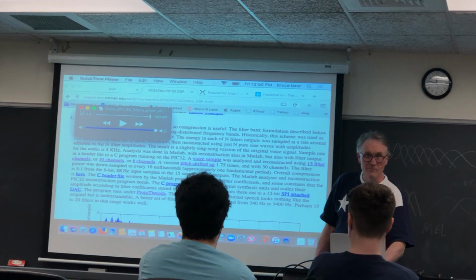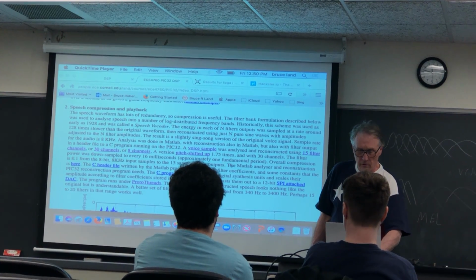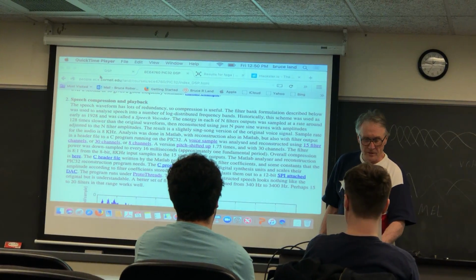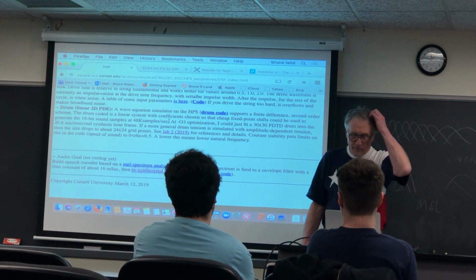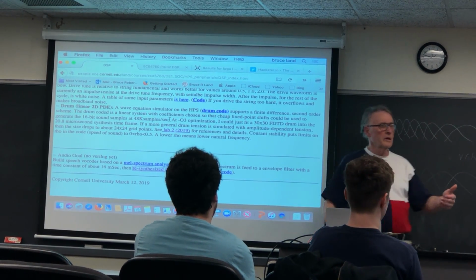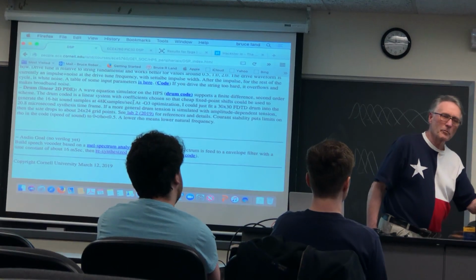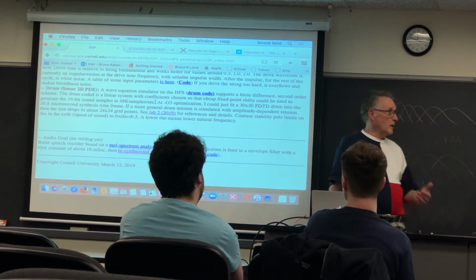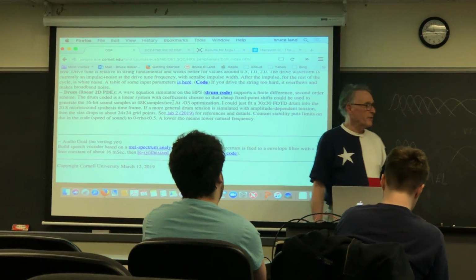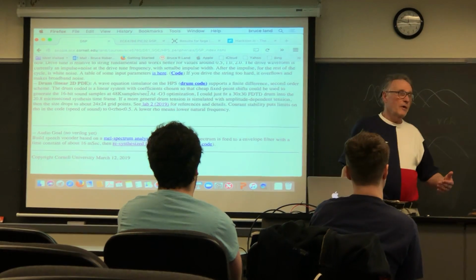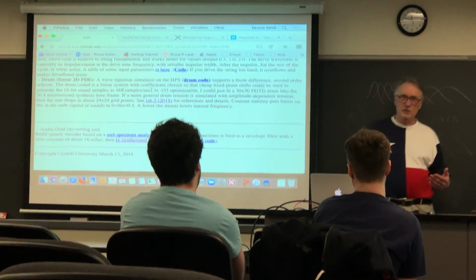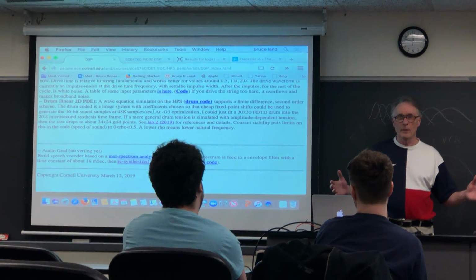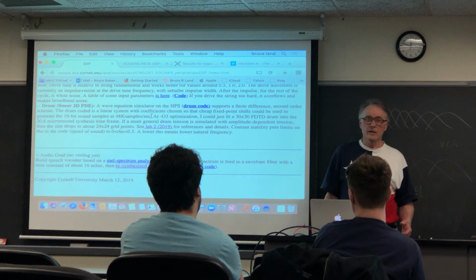Was 30 the most you were able to get on there? Oh, no, you can put hundreds on there. But what I was interested in for the 4760 page is how few could you use and therefore compress speech for playback, so that you wouldn't need as much bandwidth to transmit the data or store the data. For doing a speech vocoder on FPGA, you'd probably go to more than 30 channels, where you have a ton of CPU power, and then do interesting things with it.